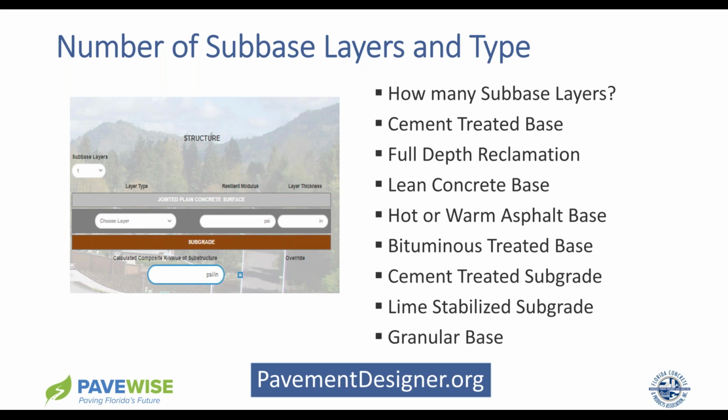And what the DOT likes to do too is add some emulsified asphalt. A lean concrete base, some people use that. Hot or warm mix asphalt. The DOT uses a hot mix base. Bituminous treatment, a cement treated subgrade, lime stabilized subgrade, or a granular base. Those are your choices.